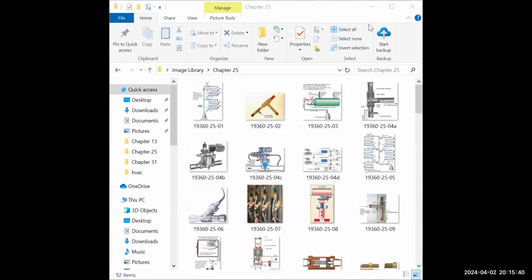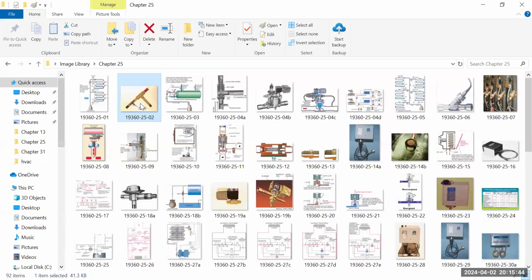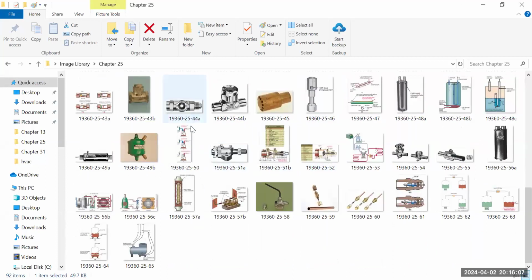So you have what they call an EPR valve, an evaporator pressure regulator. When you look at this, there's no wiring on this. This is a mechanical control. And then the CPR valve looks just like the EPR valve. This is strictly mechanical. And it's modulating fluid flow.